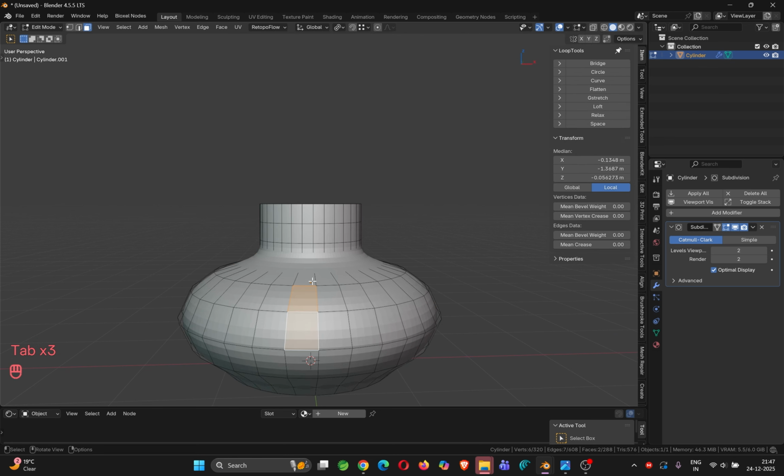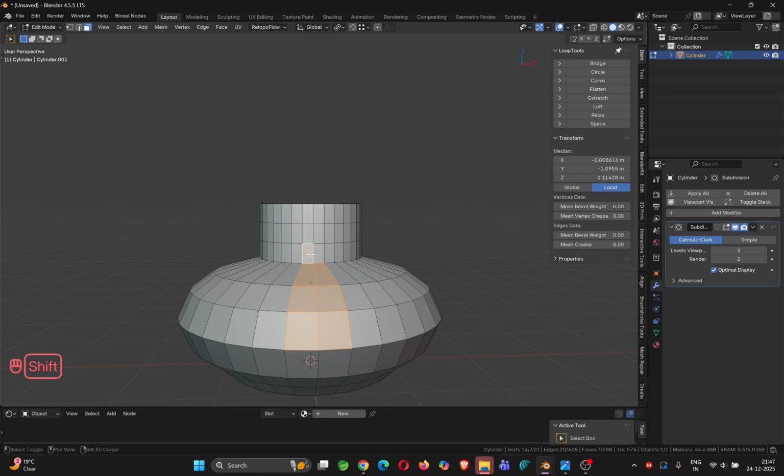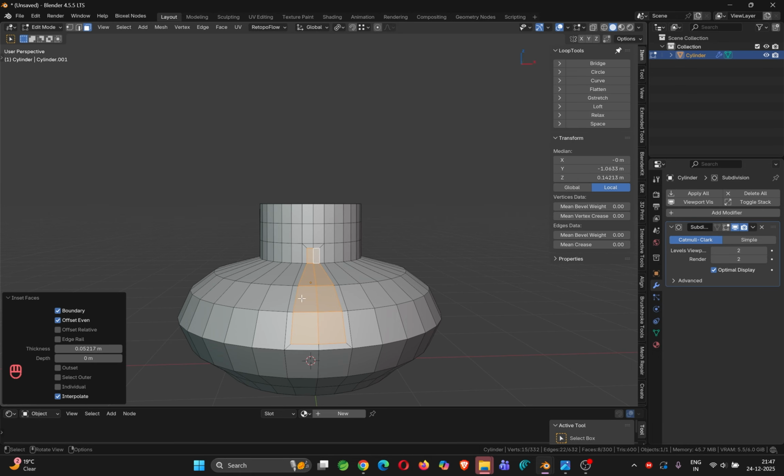So for example, say you want to create a groove shape here. Let me disable that edit mode for the time being, and say you want to do this kind of thing, right? I'm just trying to create a groove shape here, and let me extrude this face along normal, and you will see that I'm getting a shape like this. But the problem is that some parts of the faces here will create a lot of problems, and trust me when I say I am speaking from my experience. In your mesh, it is better to have a nice face distribution. The faces should have equal length to have the optimal quality.